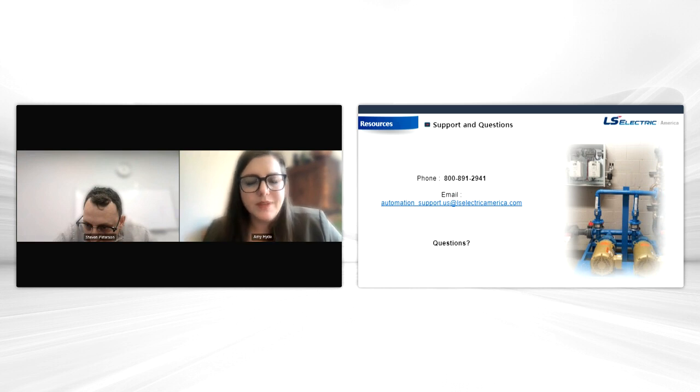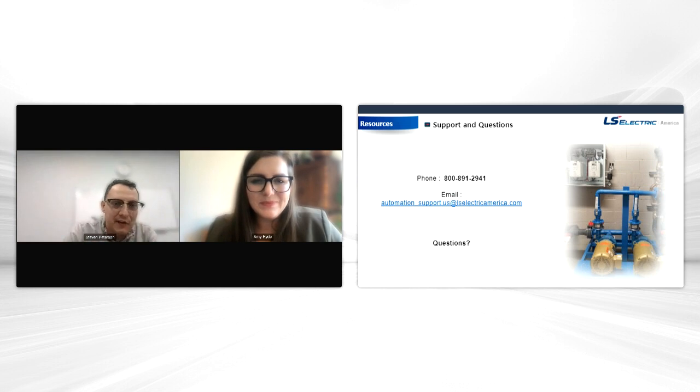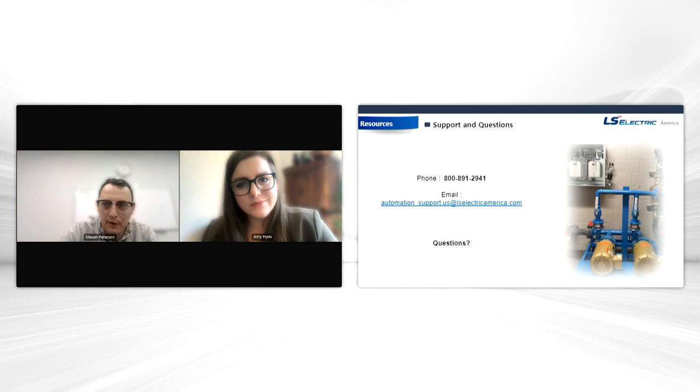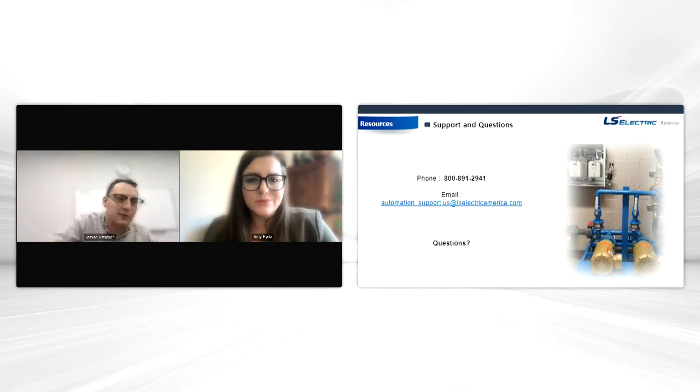Pipe break, okay, yeah. So pipe break detection, essentially it looks at speed and feedback. I didn't have it on here, but I always have other slides somewhere. So when your feedback drops, the drive speeds up to build up pressure. So you could set up a time delay. If your pressure goes below a certain point and your speed goes up to a certain point, we could assume something's wrong. And then you could do a warning, which means keep running but flash on the keypad, or you could do a trip where you stop. So yeah, that's how that setting works.